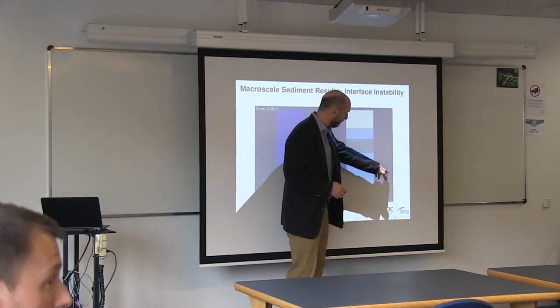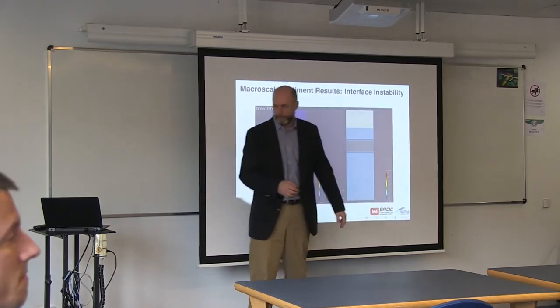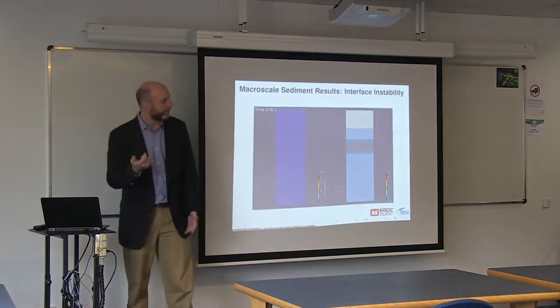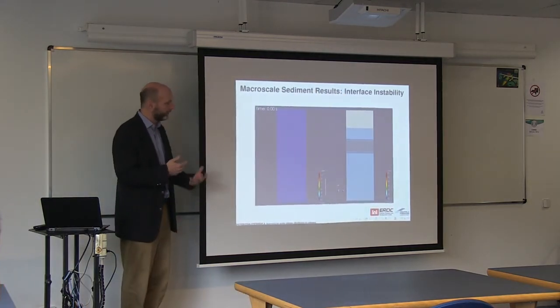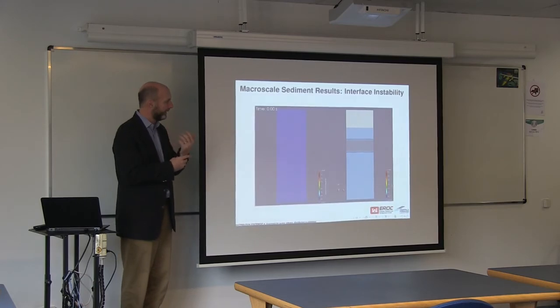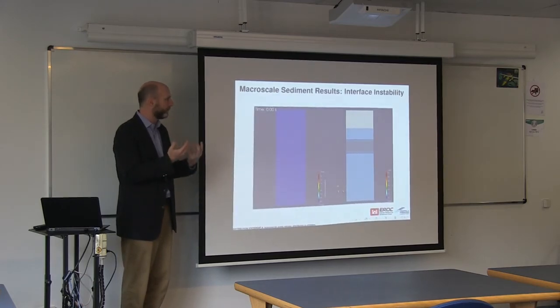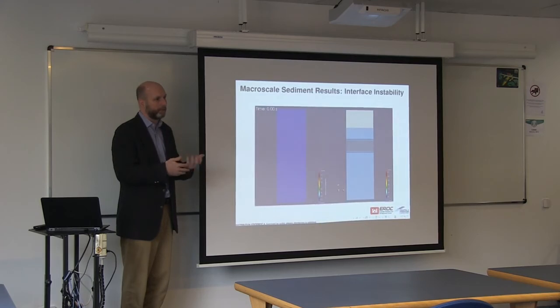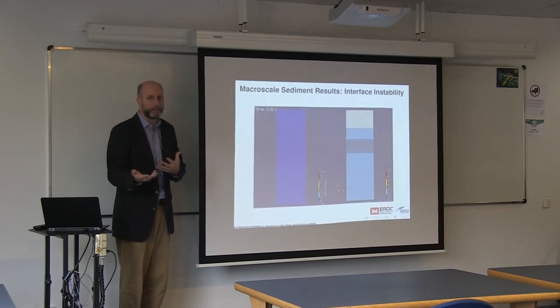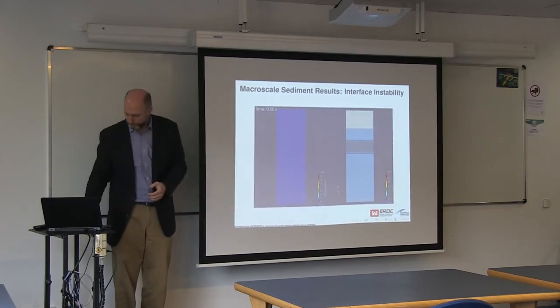In this case, the volume fraction is limited to be under 0.75. And while the constitutive relations in an ideal world are constructed in such a way that the volume fraction doesn't violate that, your numerical method won't necessarily do that, and so you'll get overshoot.